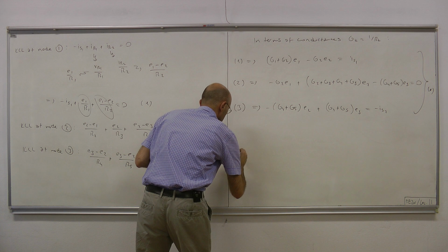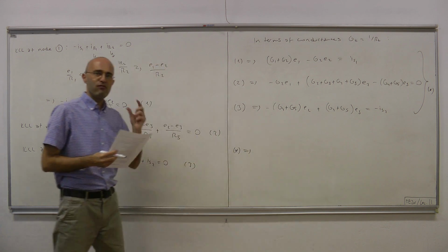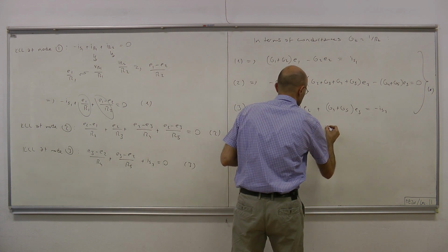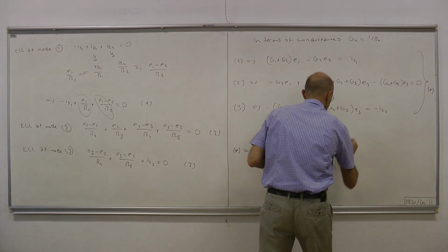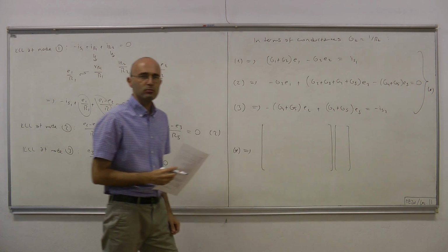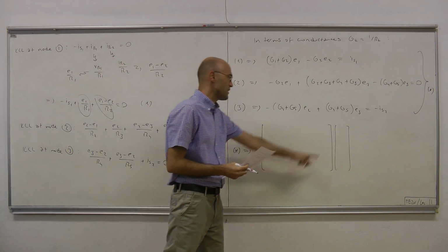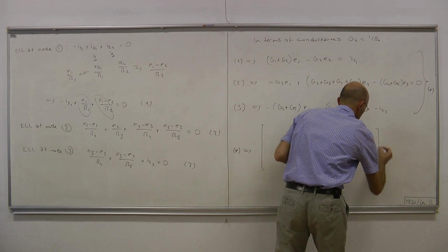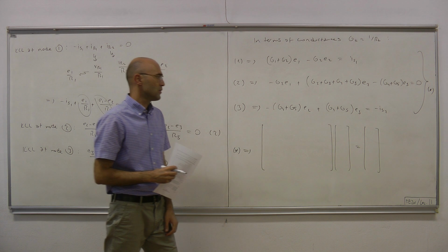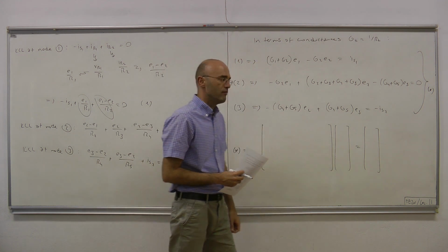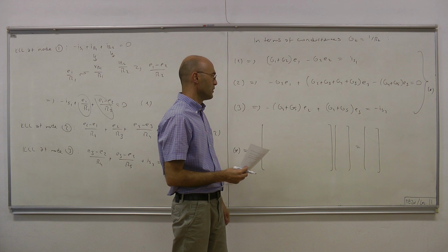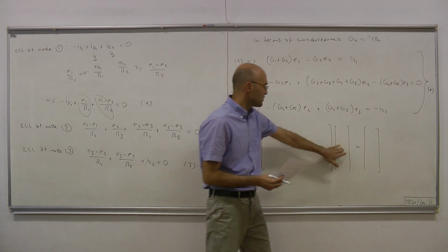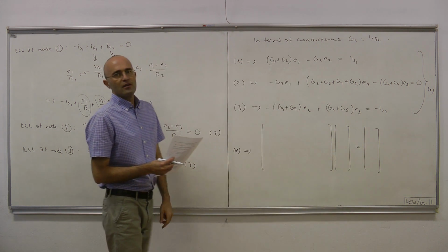And now finally we put that set into a form that computers like. This is matrix form. Some square matrix multiplying the vector of unknowns. In this case it's node voltage vector, and on the right hand side we have a vector of knowns. Okay. To figure out the unknown vector, all we have to do is multiply both sides by the inverse of this matrix. Okay, therefore, the answer equals inverse of this matrix times the vector of knowns.